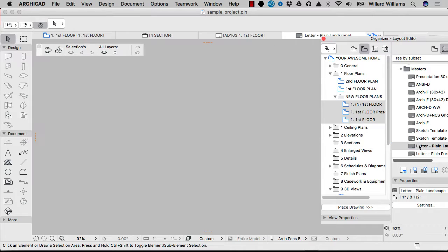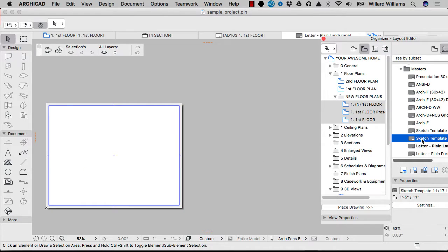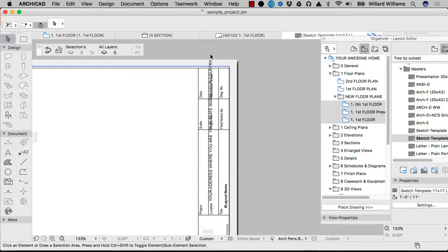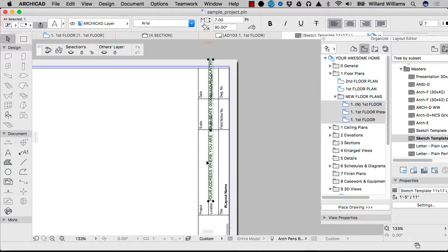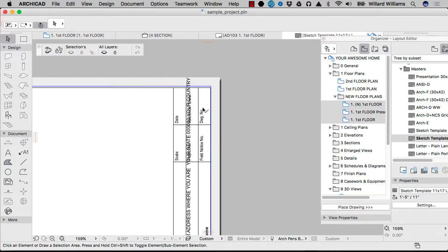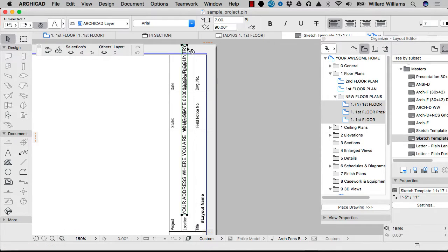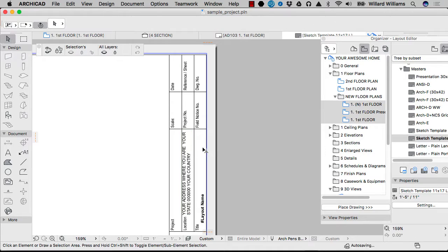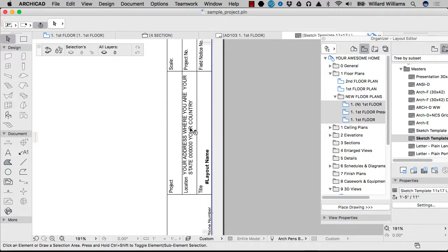If you go to our sketch drawings, this is primarily the reason I see people adjust it physically instead of changing it in the info box: you'll have instances like this where you don't catch it until after you've printed out 20 drawings or whatever. But you can go in here and adjust the properties of this automatic text without having to retype all that information.